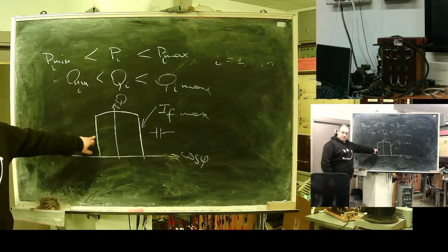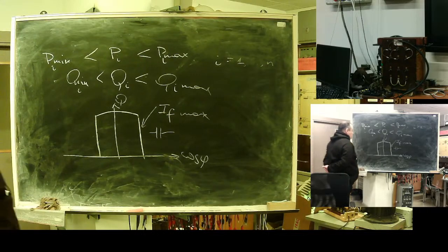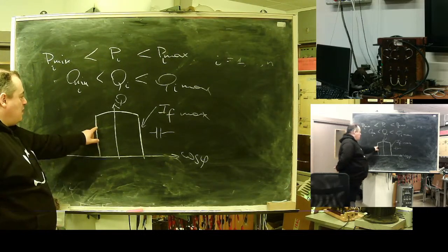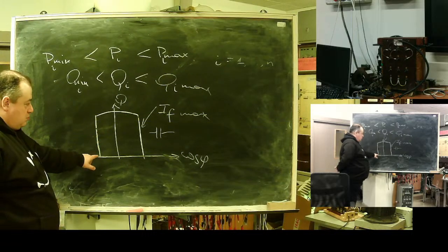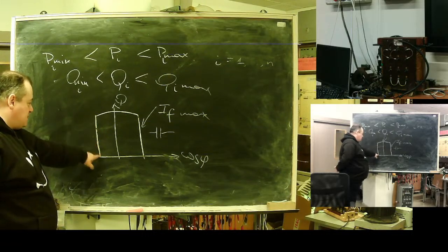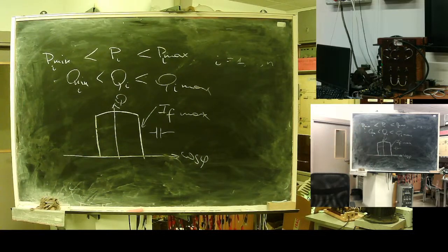Why this line? What's the limiter of this line? This line is set by generator stability. If you drop the excitation current below this margin, the synchronizing moment will be too small, and your machine will make an asynchronous turn, meaning huge mechanical load.